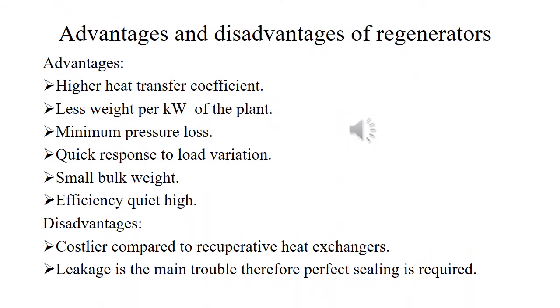Here are some advantages and disadvantages of the regenerator. First, the advantages of the regenerator: it has a higher heat transfer coefficient, less weight per kilowatt of the plant, minimum pressure loss, quick response to load variation, small bulk weight, and efficiency is quite high. Along with these, there are some disadvantages related to regenerators. It is costlier compared to a recuperative heat exchanger, and leakage is the main trouble, therefore perfect sealing is required.